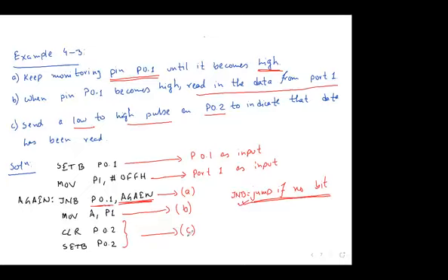So when your microcontroller sees that you are setting the value in that bit as 1, it will understand that it will read data from that device, because that pin has been configured as input. So the target will be to read data from that device. This set bit value will not be checked with the JNB instruction. This is a difference between a pin value and the latch, and I don't want to go to the latch portion.